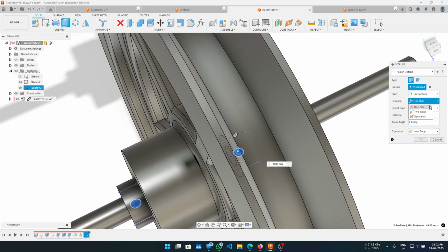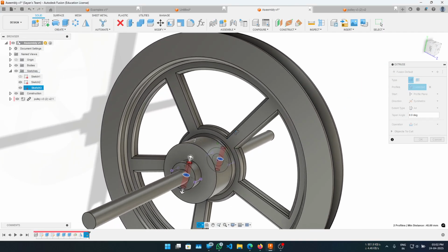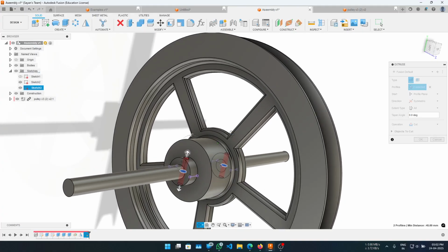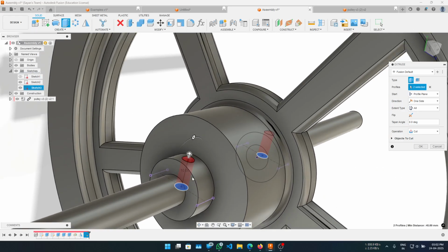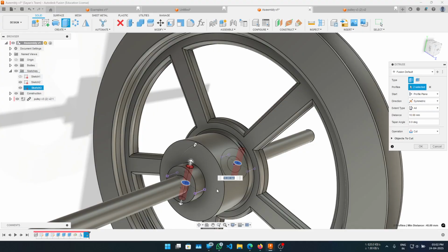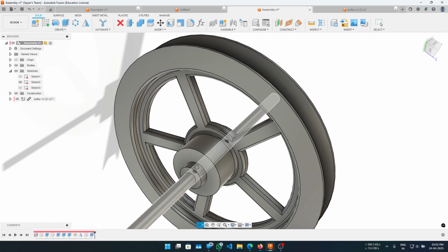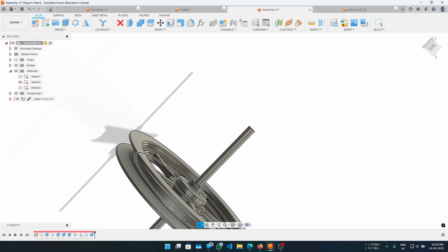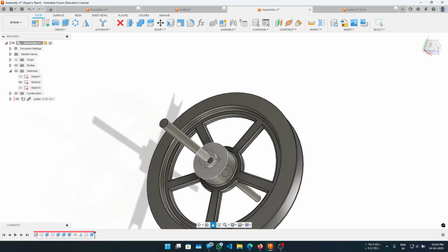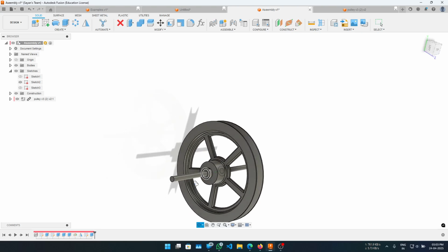How much should it go? It should go symmetrical, so it's a through hole. Or wait, maybe no, it's not a through hole. It's just one side. Depending on the design preference, either way works. Even a through hole works here. You'll just need a bigger screw. That's all. A screw on top and the nut at the bottom and then secure it properly.